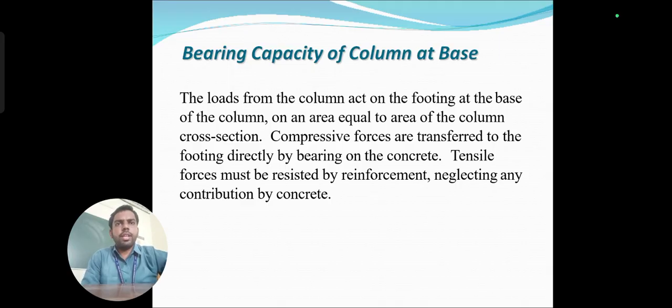And after that, the bearing capacity also. Compressive forces should be transferred to the footings directly by the bearing of the concrete, and tensile forces must be resisted by the reinforcement, neglecting any contribution by the concrete. Why? Because concrete is only responsible for compressive forces, and the tensile stresses are the responsibility of the reinforcement. From this situation we have to find the critical section on that footing.